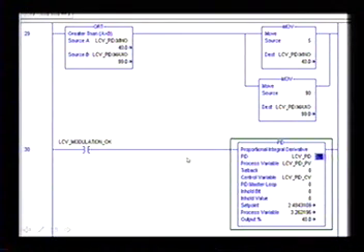Okay, so go back to the PID. Here we've dropped in the PID instruction. If the level control valve modulation is okay and all the data validation is okay, this should run and it'll actually control that process. Again, the objective here is what? For the process variable to equal the set point. You can see they're not equal right here, so the output will open or close depending on the control action, and it will try to correct that so that these two values are equal.